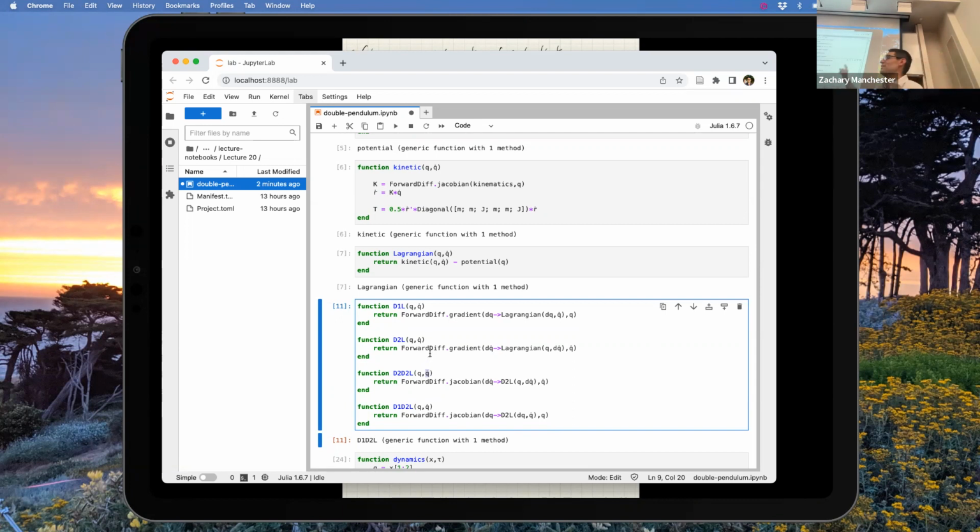So if you write down a weirdo Lagrangian in any kind of weirdo coordinates, and you want to know what the mass matrix is, and you didn't explicitly compute it, and you wrote down this big expression for a Lagrangian, the mass matrix is the Hessian of the Lagrangian with respect to the q dots. That's what it is. Maybe that makes sense. It's always q dot transpose M q dot, right? That kind of thing. So if you do that, you get the mass matrix.